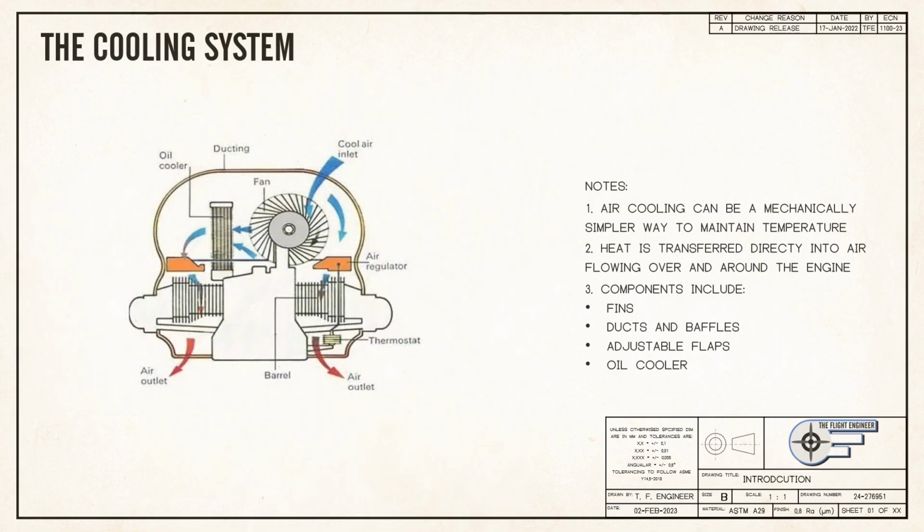It's worth noting that air cooling and liquid cooling can be combined in some cases. This typically manifests as an engine with air cooling fins on the cylinder and water cooling jackets on the cylinder head, where heat generation is most intense.